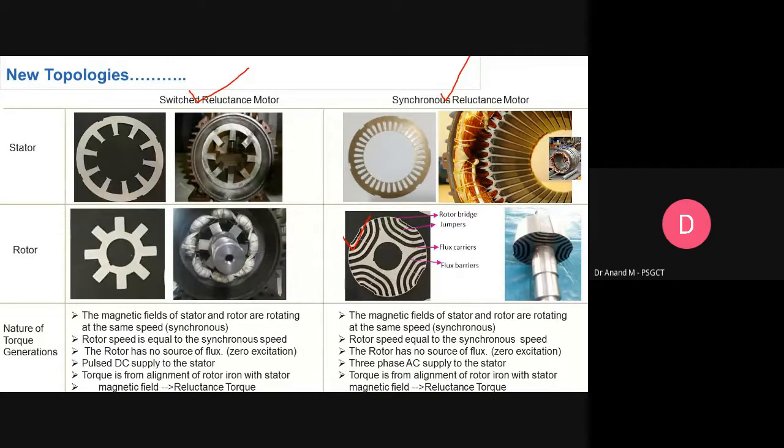But the only drawback, as far as the power drive is concerned, is the power factor. But even till today, not in an EV, you can consider the industrial grade motors. If you consider the branded OEMs, for example, KSB type of manufacturers, it is well proven that IE4 kind of efficiency is achievable even in synchronous reluctance motors.